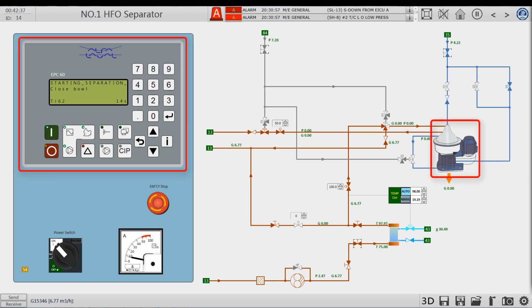It is going through a series of fault diagnosis tests. During this time, the oil separator will perform a leak test to detect any leakage inside the separation cylinder. The test method is to close the oil inlet pipe, the oil outlet pipe, and the water outlet pipe, and observe whether the pressure inside the separation cylinder decreases in the rated time.